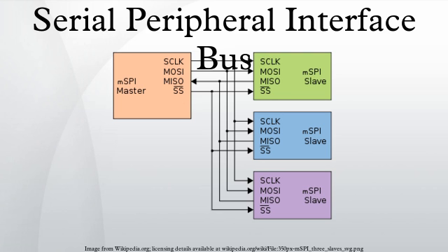Data transmission. To begin a communication, the bus master first configures the clock, using a frequency less than or equal to the maximum frequency the slave device supports. Such frequencies are typically up to a few megahertz. The master then transmits the logic 0 for the desired chip over the chip select line. A logic 0 is transmitted because the chip select line is active low, meaning its off state is a logic 1. On is asserted with a logic 0.